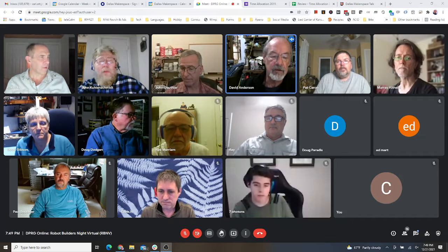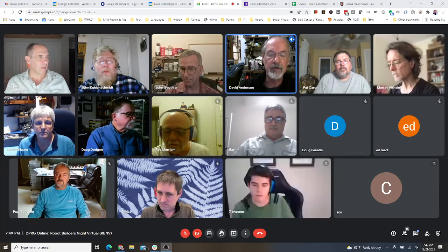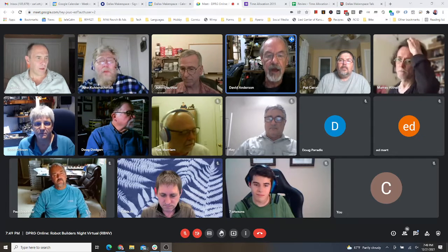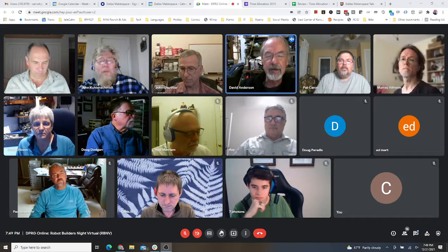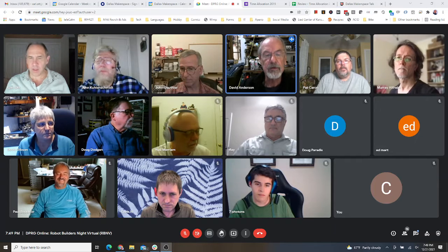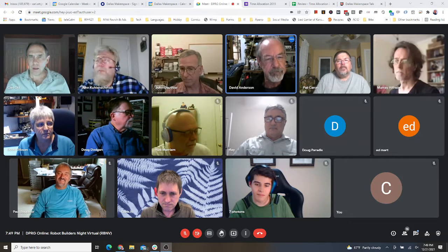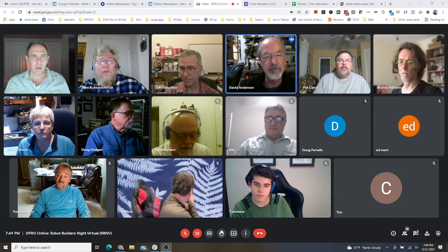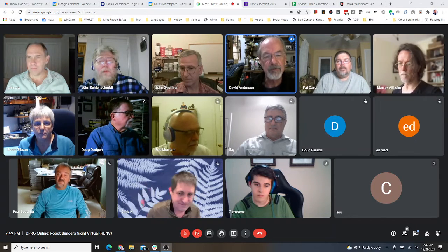I will say on the RCAT robot, where I spent the most time trying to tweak and hone the odometry, the building next door to mine has this gorgeous flat marble floor. And the wheel odometry actually does better on that floor than the gyroscope does. But that's the only floor in the universe where the wheel odometry does better.